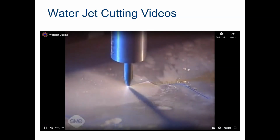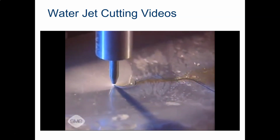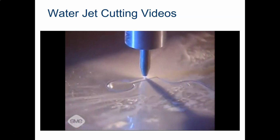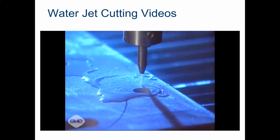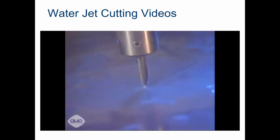The abrasive water jet erosion process uses abrasive particles suspended in a high-pressure stream of water to cut a wide range of materials. Abrasive water jet cutting generates no heat and leaves no heat-affected zone, making it an alternative to thermal cutting. In addition, there are no toxic fumes, toxic wastes, or chemicals to cause problems.